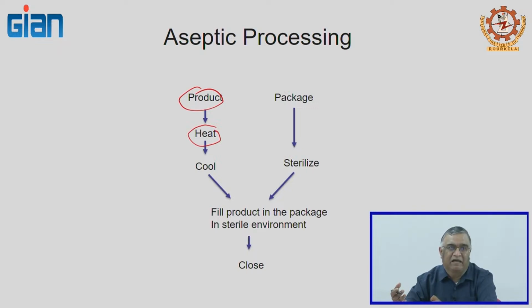One of them, for example, is the tubular heat exchanger, where you pump the soup through a central tube, and then you have an outer tube where the heating medium can pass through, thereby heating your soup. Or you can have a scraped surface heat exchanger, where you have a similar mechanism, but also you have an agitator which mixes the soup as it's being heated.